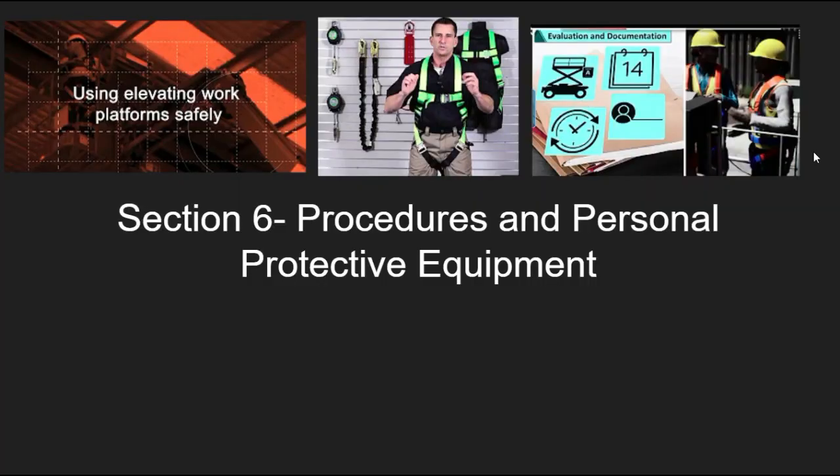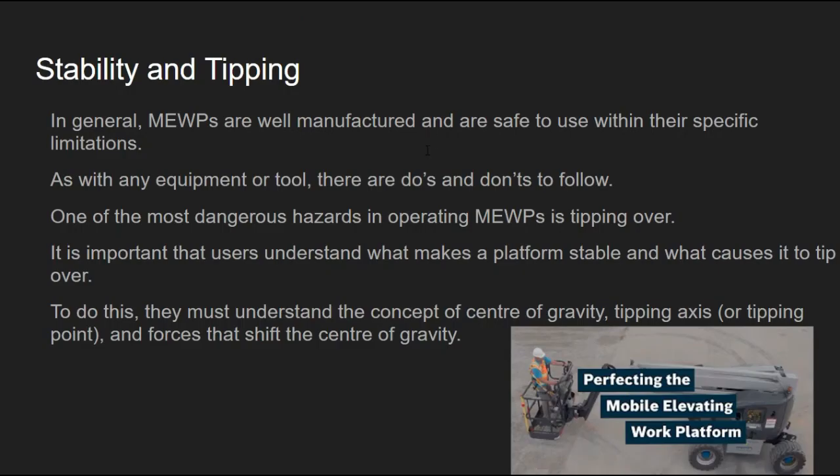Section 6. Procedures and personal protective equipment. Stability and tipping. In general, MEWPs are well manufactured and are safe to use within their specific limitations. As with any equipment or tool, there are a lot of do's and don'ts to follow. One of the most dangerous hazards in operating MEWPs is tipping over. It is important that users understand what makes a platform stable and what causes it to tip over.